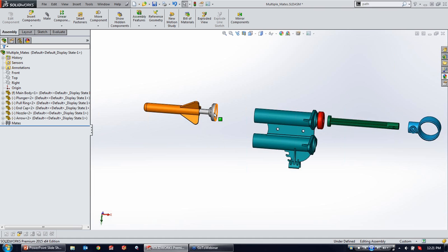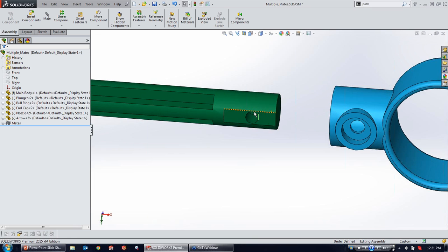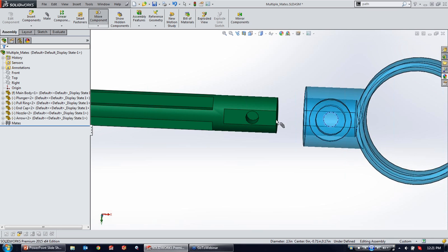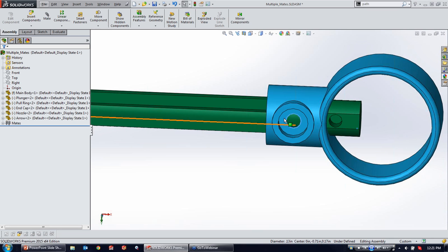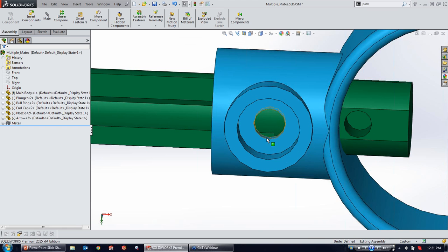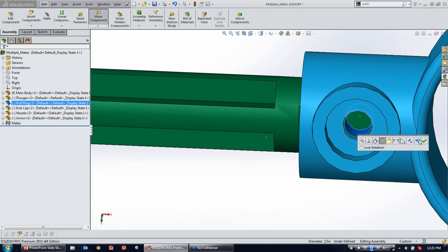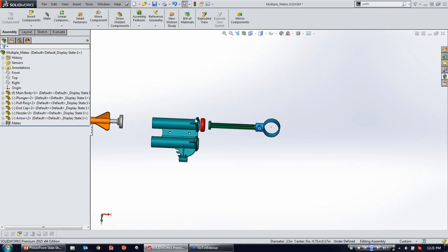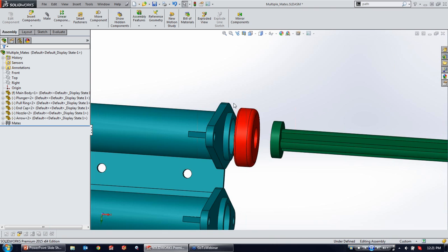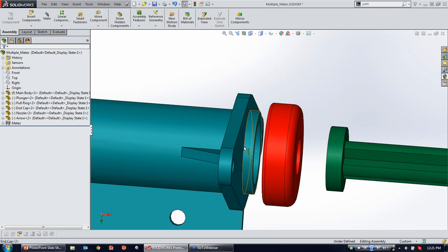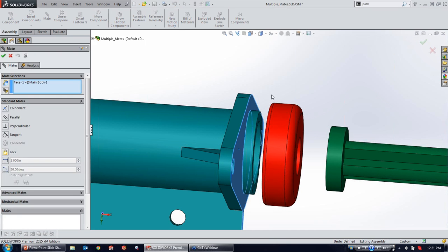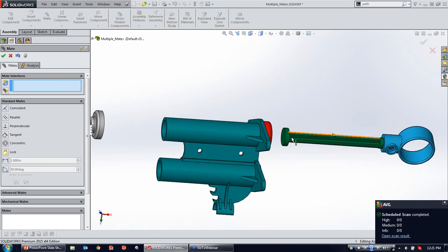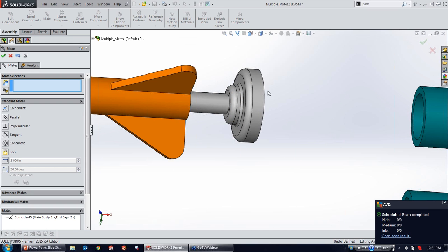All right, so now a couple other mates that I want to add. And I'm going to use Smart Mates for this, so select, hold down Alt. There we go. Get them concentric. Now they're going to move together. Maybe we'll throw just a quick mate here, so those are connected. Slide this up, and we'll do one more.